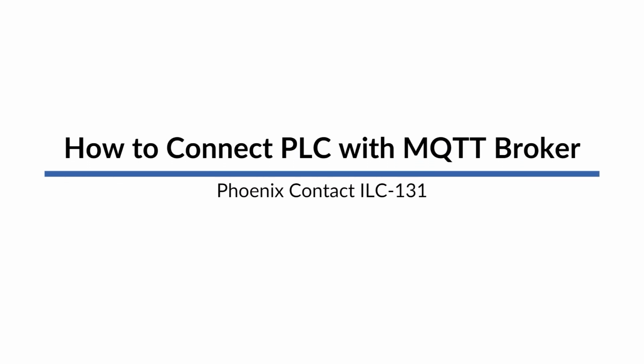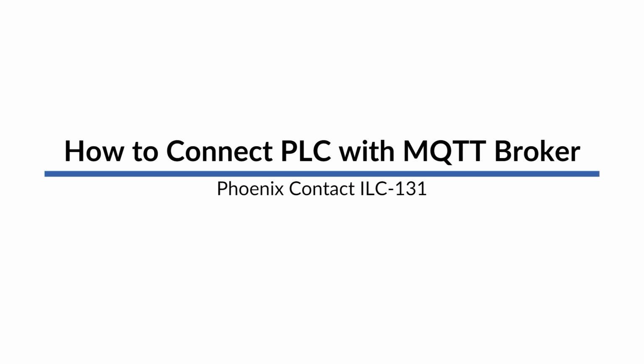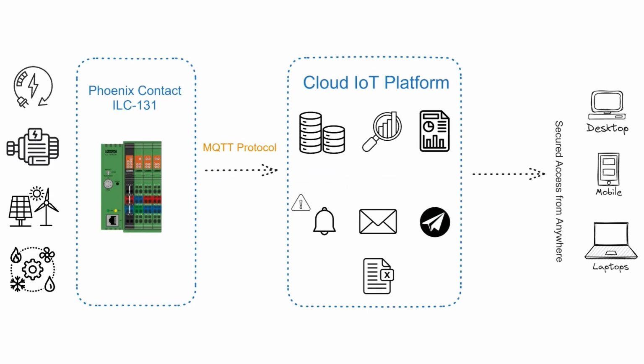Hello everyone. Today we are going to see how to configure the Phoenix Contact PLC ILC-131 to push data to a cloud platform using the MQTT broker. First, let us see the basic architecture diagram. Here we are sending data from critical industrial equipment through ILC-131 to any cloud IoT platform using the MQTT protocol.